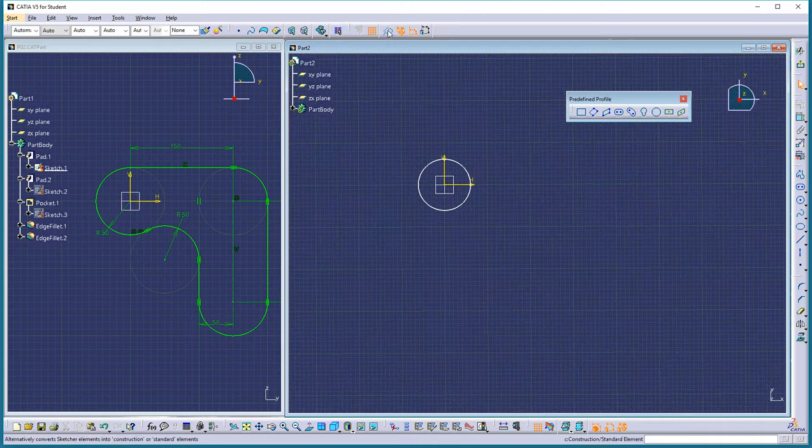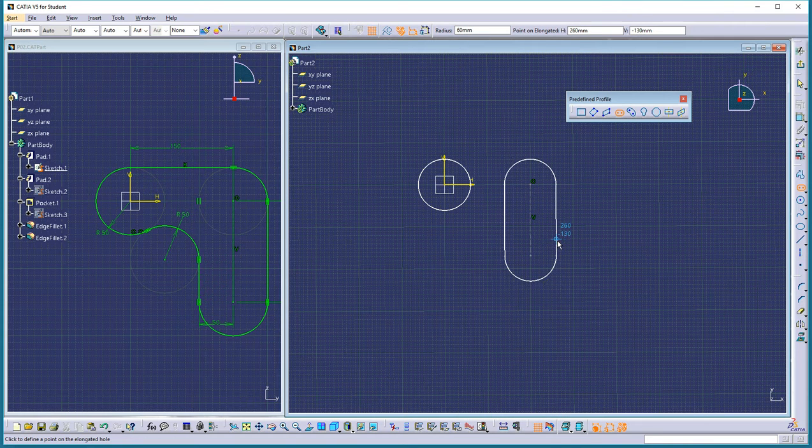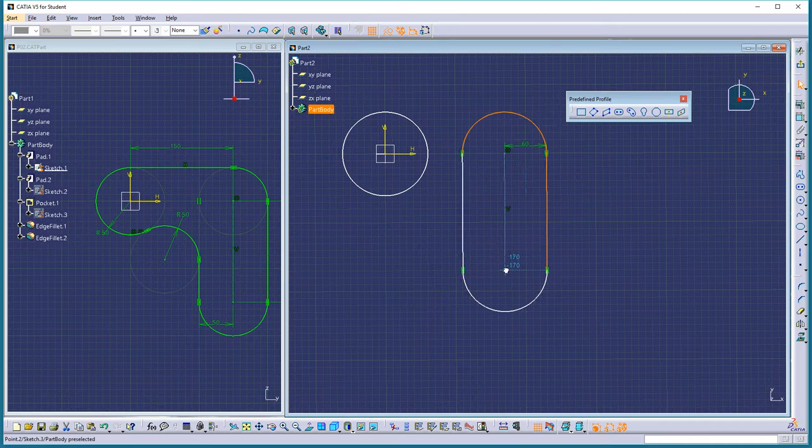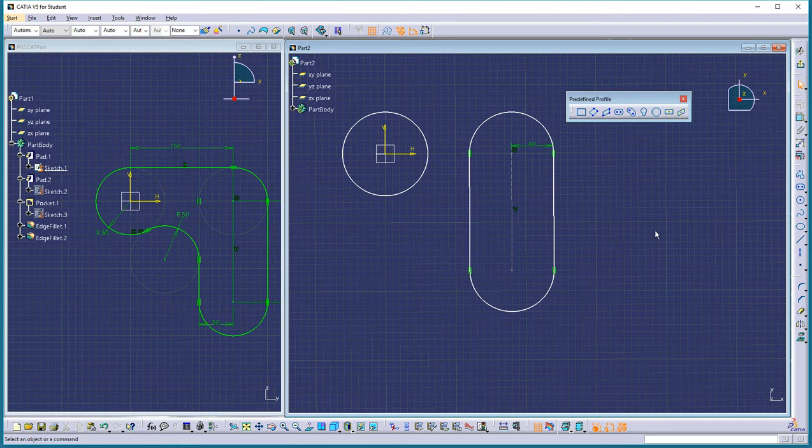Now I want to make sure that I have my geometrical constraints on, and I want to pick here, and then I'm going to come down, and I'm going to make this also about a radius of about 50. I think I got 60 about on both, but that's fine. Now this can go back and forth, but I picked up this geometric constraint to constrain it to the origin along here. So that's perfect. So that keeps these two lined up. And of course this can go up and down either way. So let's move it about in position, about something like that.